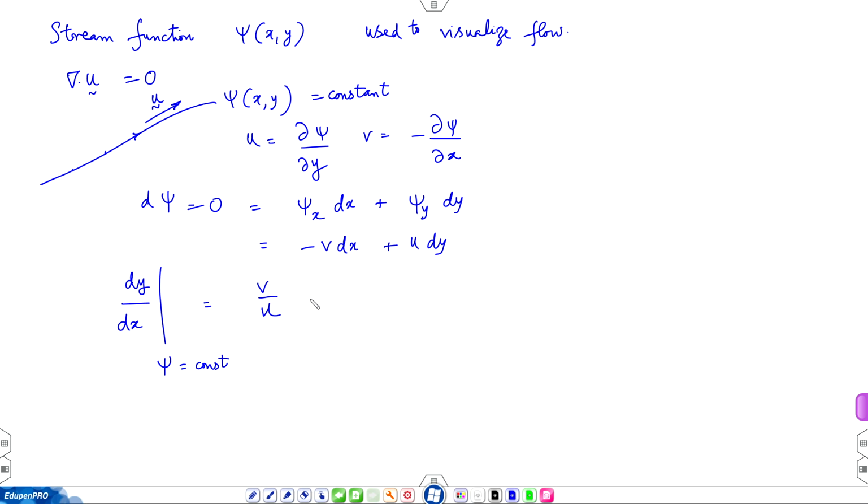So, how is it connected to the mass balance equation, or del dot u equal to 0? By the way, there is a profusion of terminology. The original form of the mass balance equation, which includes density, you refer to as mass balance. When you write del dot u equal to 0, it's sometimes called the continuity equation. What is continuous? It's the flow rate. Flow coming in is equal to flow going out. There is no accumulation of matter. There is no change in density. It's a continuous flow. It's called the continuity equation.